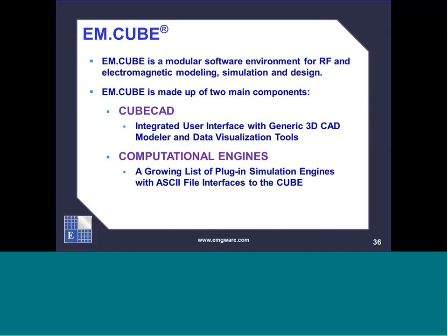So EM.Cube is a software that has a couple of different simulation engines. We have FDTD, we have the planar method of moments, we have 3D method of moments, we have a physical optics simulator, and a ray tracing simulator. Basically it is a simulation software foundation that has a common CAD and visualization framework, and many different computational engines can be plugged in.